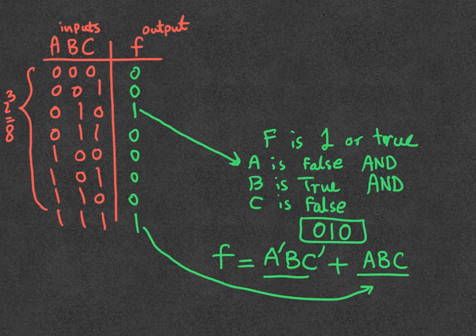Yes. So we say AND, we get AND here. Yes, the dots are the ANDs. So since we say F is true, if F is 1 or true, when A and B and C, or for this case, that's why we get OR here. For these two cases are going to be 1. That one or this one. That's why we get the OR function here. We're going to see this in more detail later. Don't worry. So this is just showing you that we can write a Boolean expression from the truth table.